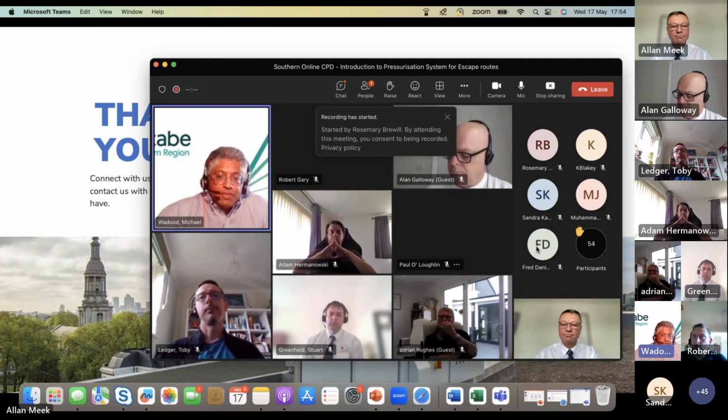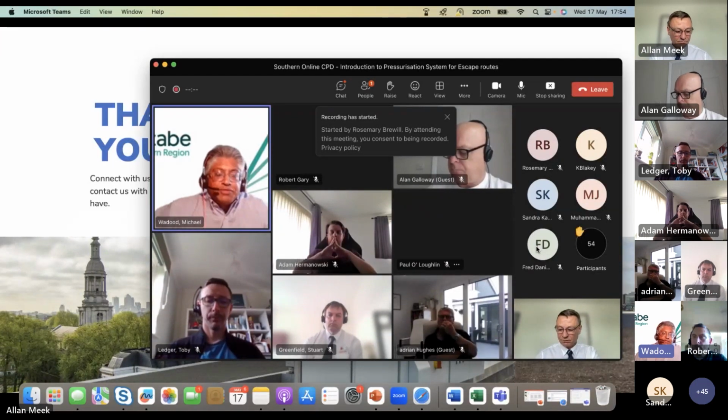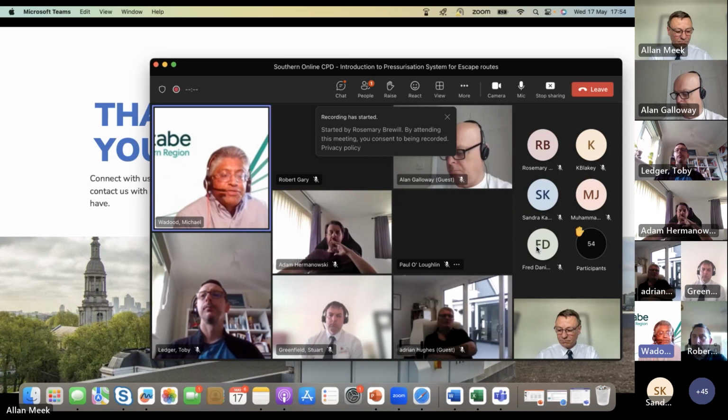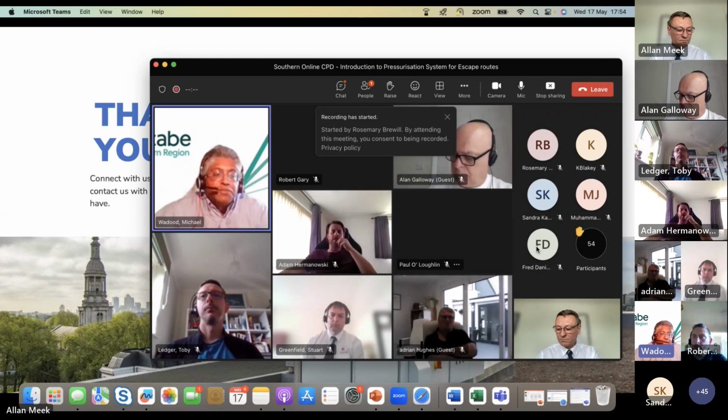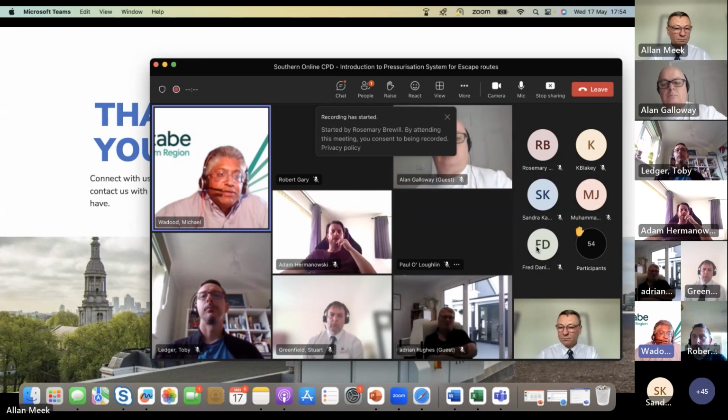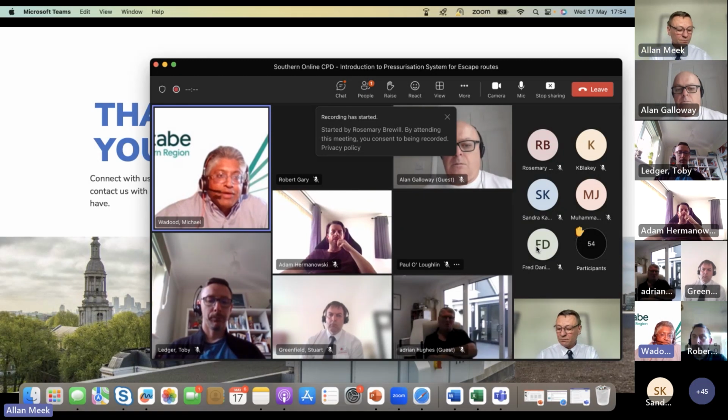Okay, so I have a question. In pressurization, you have a building that's been pressurized, it's in a fire situation and people are escaping. The fire brigade then turn up and decide that they want to evacuate 2 floors using the new emergency evacuation system. How does that affect the pressurization system when you have 2 doors on a staircase opening? Because the pressurization is just relying on a fire on 1 floor and it working out on that basis.